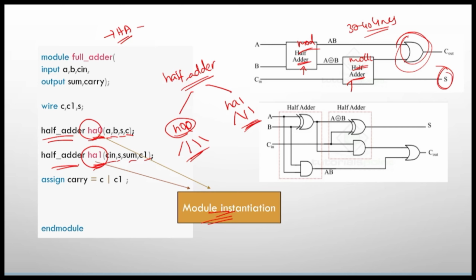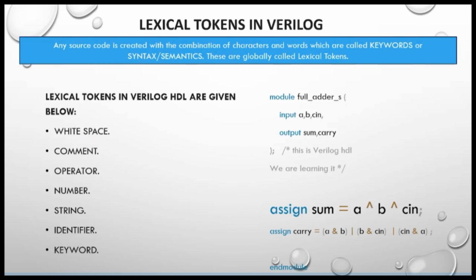Why? As I told you in the VLSI design flow, in verification the verification engineer will be sending some stimulus to the RTL. So how will you send the stimulus from the test bench to the RTL? You need a connection. By instantiating that design in the test bench, you will be connecting these ports and those ports. You will discuss it in this video itself. I'm just giving you a hint of what instantiation is and where it is actually used. So this is about module instantiation.